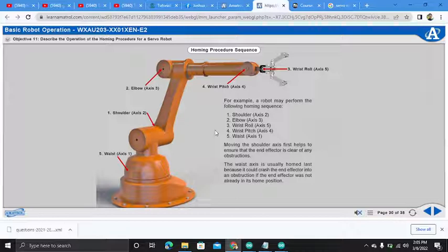List two types of gripper finger designs and describe their operation. Grippers are available with several types of finger designs to allow them to best handle a part at the least cost. There are two common types of gripper, guys: the two-point curvilinear and the two-point parallel. Two-point curvilinear grippers have two fingers that close on the part.